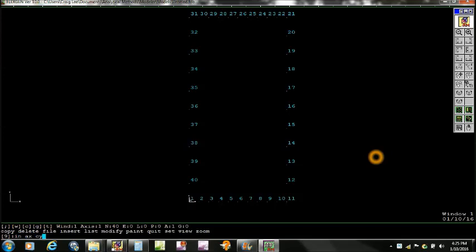So now I want to insert a circle here, or create a circle. So I'm going to insert an axis system, a cylindrical axis system, at the center of the circle. And there's a couple of questions that need to be answered about the orientation of the axis system in space. We do that, and it appears, as you can see right there. So that's the center of the circle.